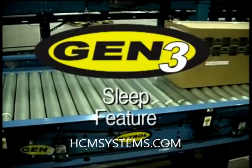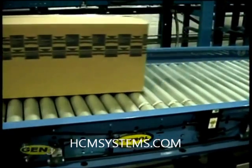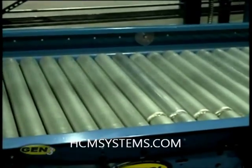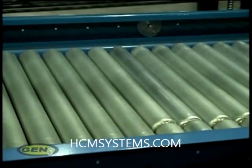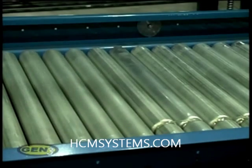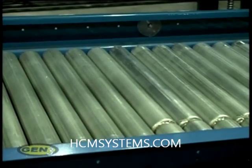Sleep feature. Conveyor zones that have not seen any carton activity for a selected period of time may be set to go to sleep or stop driving until activity is detected. This reduces noise and component wear, and reduces energy consumption while the conveyor is temporarily clear of cartons.